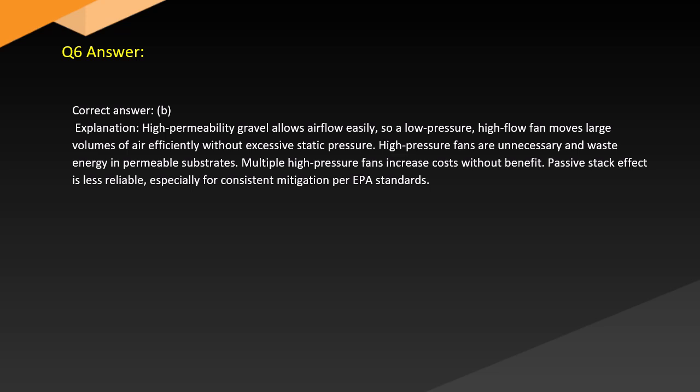Answer. Correct answer: B. Explanation. High permeability gravel allows airflow easily, so a low pressure, high flow fan moves large volumes of air efficiently without excessive static pressure. High pressure fans are unnecessary and waste energy in permeable substrates.